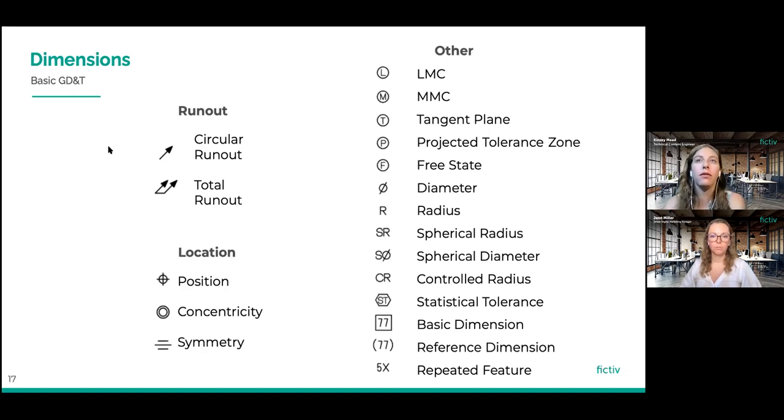It looks like we have a question here. What if your groove width is the most important? So that can definitely occur. If that groove is being used to mate with another part, then you may want to find a way to use that as a datum surface or feature, which is totally possible. And again, that gets a little more in the weeds with GD&T, but great question.